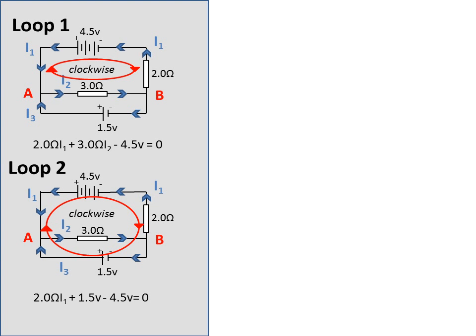Now we have two examples here. Here's my first voltage equation for loop 1, and I've done another one here for loop 2. For loop 2, I've gone through the 2 ohm resistor again, and I have 2 ohms times I1, plus I've gone through the bottom path.